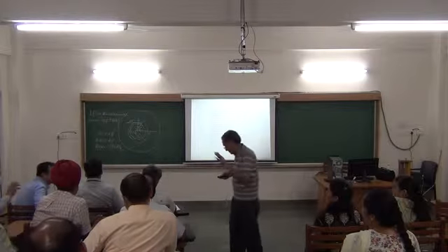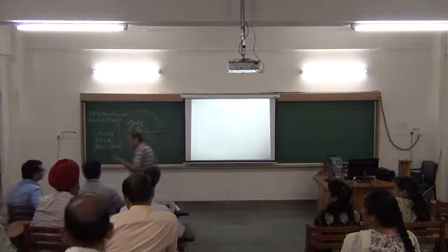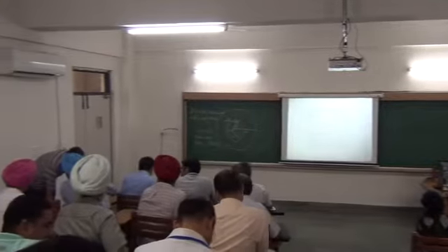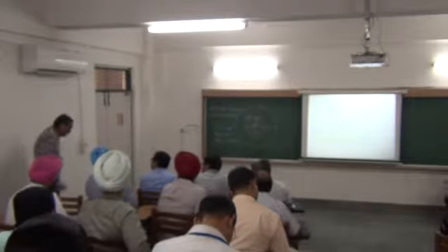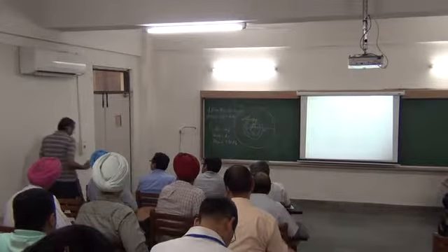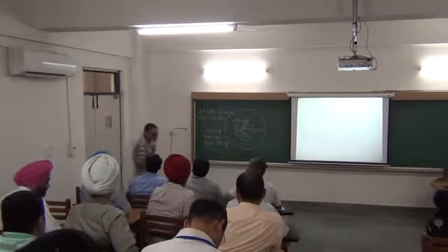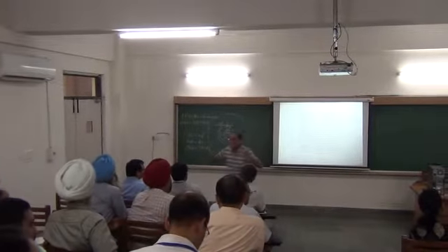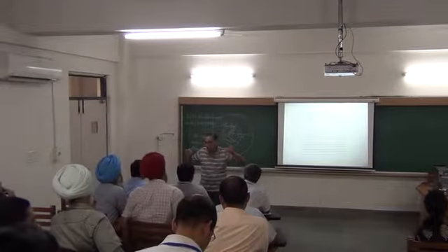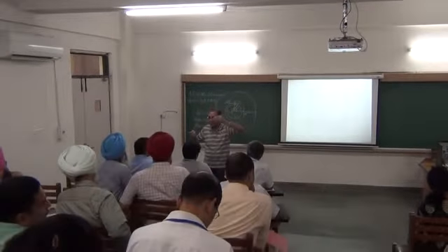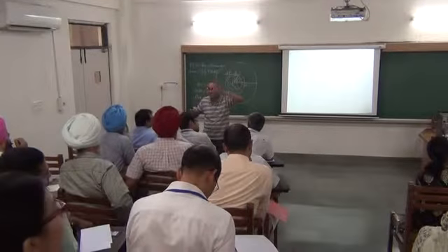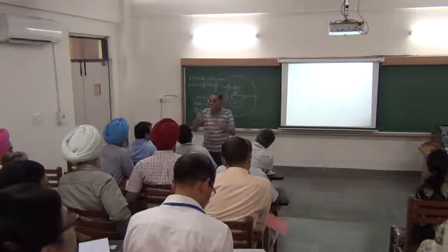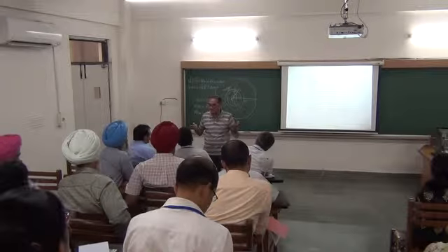Can you check the quality of brass? I don't hear that completely. Can you check the quality of brass by using the modulus? See, okay. If you want to test the quality of brass, you must first take brass with different known compositions, say zinc 20%, 25%, 30%. You must measure the rigidity modulus for these different compositions. Then you can test it.